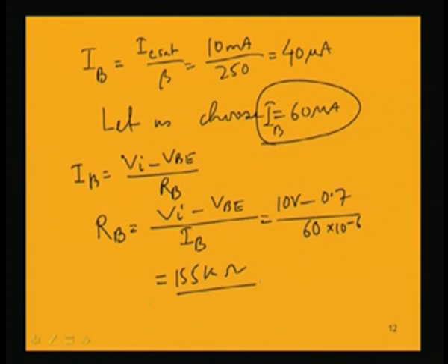But as we are designing the circuit, practically it is better to take standard values of resistances, because the resistances we will have in the laboratory or real environment have some standard values, and that is why it is better to choose standard values while designing, so that our design corresponds to the actual design that can be done in the lab environment.